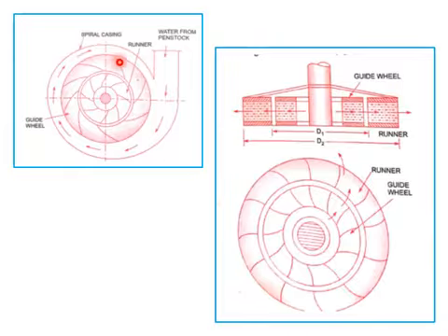So I was discussing the radial flow turbine. Here the water is coming from the penstock and goes into the casing, and the change of pressure takes place. Now water is entering here. This is the outer circumference, this will be the inner circumference. So water enters in this direction, radially, but perpendicular to your screen is the axis of rotation. Therefore water enters radially, so it is called the radial flow turbine. From the outer circumference to the inner circumference, it enters inward radially, so it is known as the inward radial flow turbine.